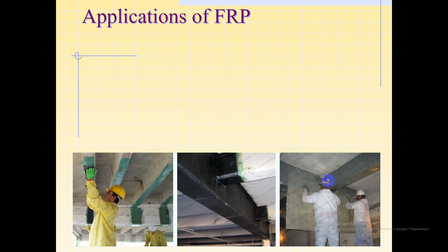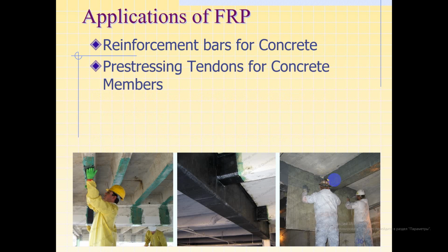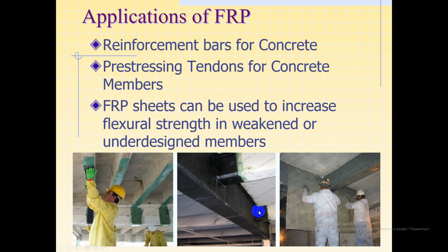Applications of fiber-reinforced polymer. Reinforcement bars for concrete, pre-stressing tendons for concrete members, fiber-reinforced polymer sheet can be used to increase flexural strength in weakened or under-designed members.